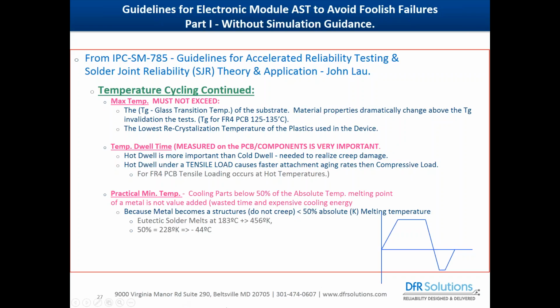So when we develop a thermal cycle, it used to be, let's say you had a lightweight module, you could do a 15-minute heating ramp rate, and then a 15-minute hot dwell, and then 15 minutes to go down to cold, and then 15 minutes at cold dwell, and then you ramp up again. So that would give you one thermal cycle per hour.